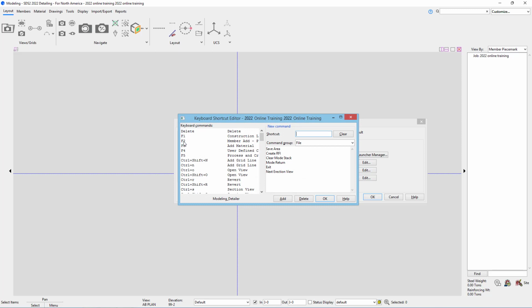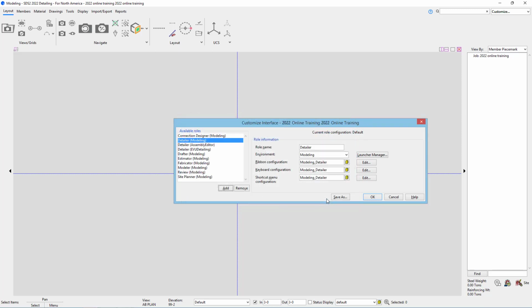we can see our different key commands as well as the tools. For this training, I have created a document that will list our keyboard shortcuts that can be accessed in our additional references section for both modeling as well as drawing editor. When we are creating our shortcuts there, if the shortcut already exists, you must delete it first and then you can reuse those key combinations. You can have multiple key combinations work for the same tool. You can't have one single key combination work for multiple tools.